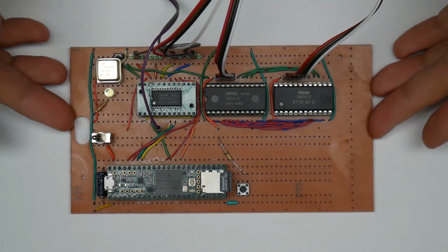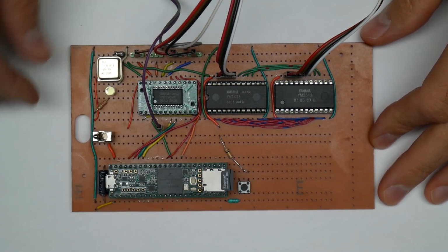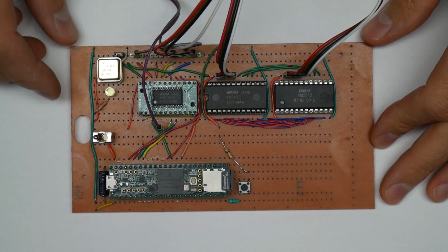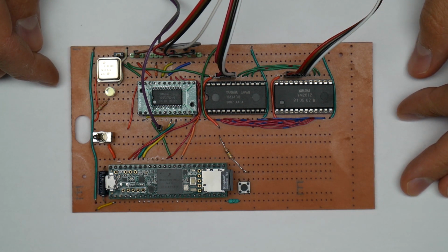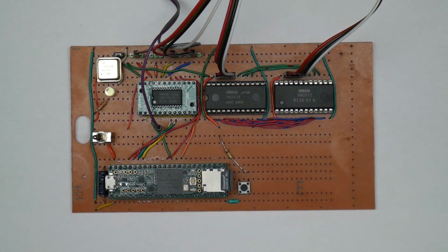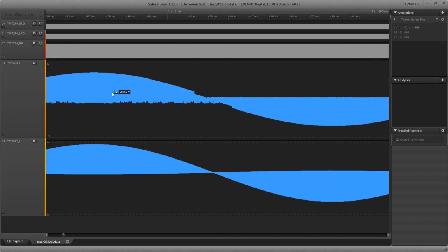Essentially, it's just an automated test rendering setup powered by a Teensy and a micro SD card. All 3 chips are clocked by the same external 8 MHz clock, and the Teensy writes are sent to all 3 chips simultaneously. So I felt it was an ideal benchmark to be able to get synchronized renders out of the 3 chips for comparisons.